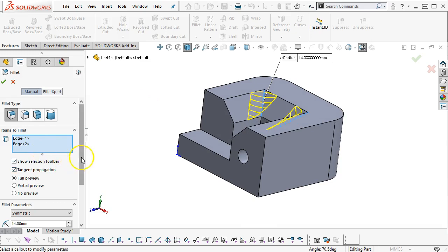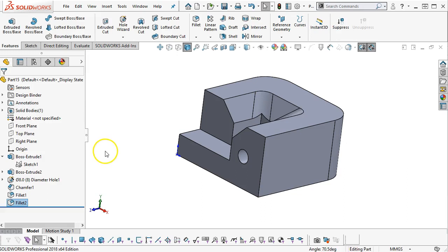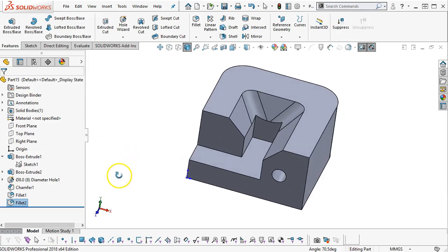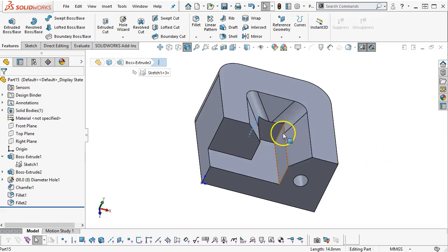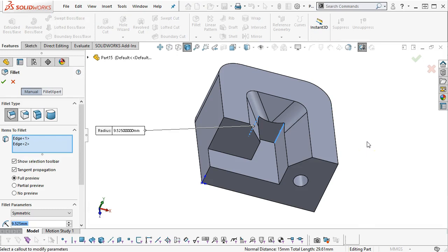All right, so we're going to come back from the 14 millimeter, and if I were to put 0.375 inches to match my geometry, that's pretty much what I'd be looking at. All right, and then we have the same problem that I can't cut square corners with round tools, so at the very least I'm looking at maybe a 1/4 inch, 6.35.